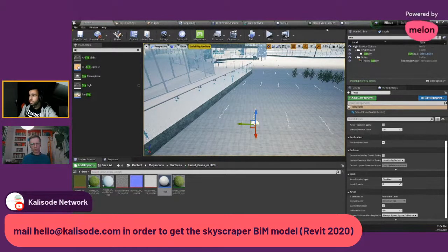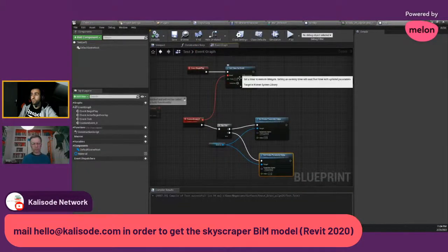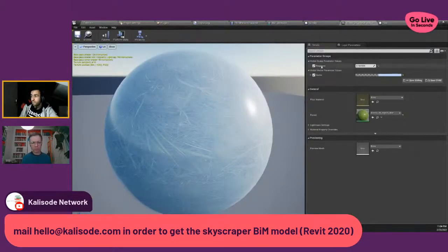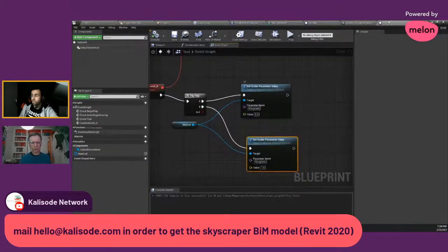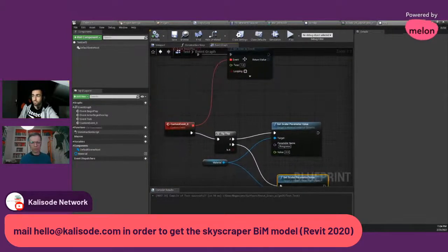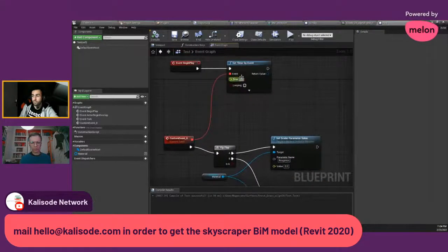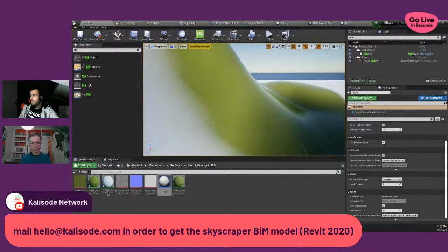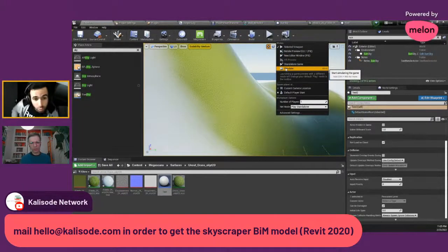So the actor that I've just created is going to change this parameter that I have set here, and it will change the roughness, the glossiness, one time to 0 and then one time to 1, and it will repeat itself every second. So let's see if it works. Dynamically. Yeah, exactly. I accessed it through the code.